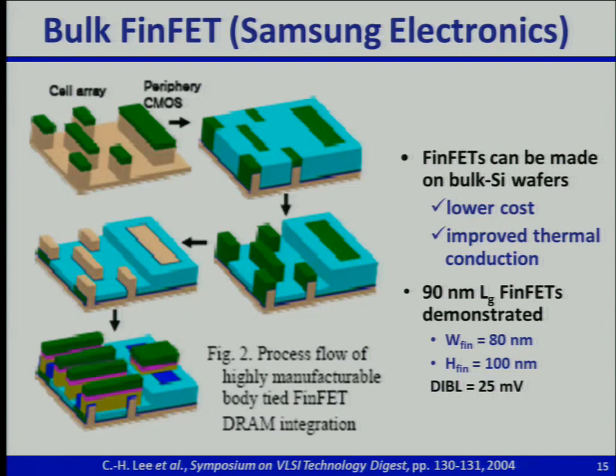Okay, so there are a couple of things here that are a little tricky. First of all, the whole reason of using an SOI is to prevent leakage. If you have a FinFET and you have a gate, if it's a bulk silicon wafer, then you actually can have leakage between the source and drain regions underneath the gate electrode, right? Because basically what they need is this.